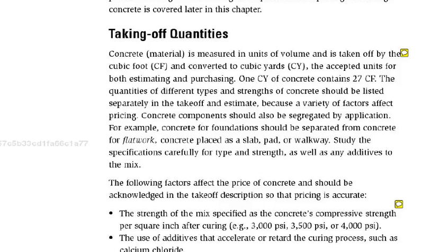So, for example, you're measuring a piece of sidewalk and it's 10 feet long, 5 feet wide, and you're going to put a calculation on your worksheet. 10 times 5 equals 50. After that, you're going to put SF, square feet. And then we know what the units are that you're working on.